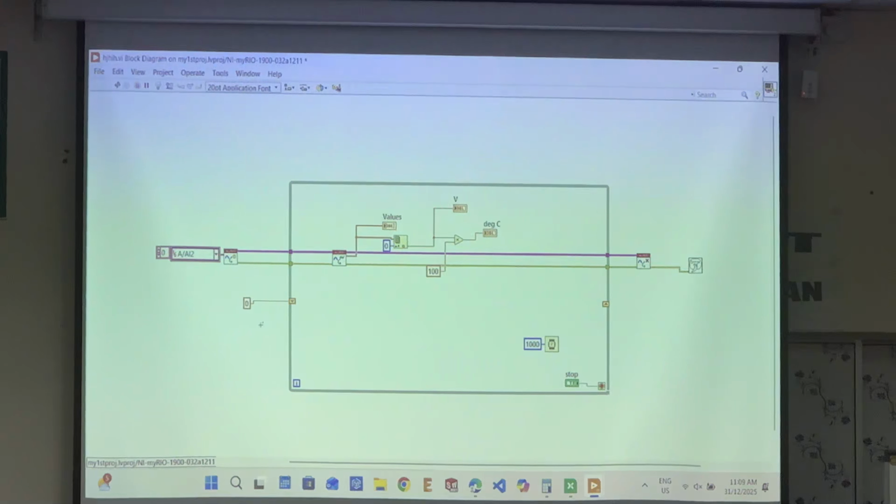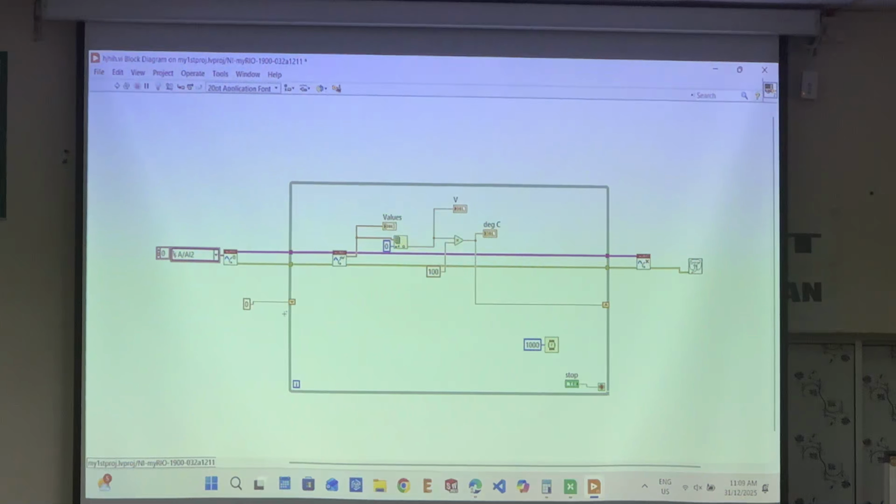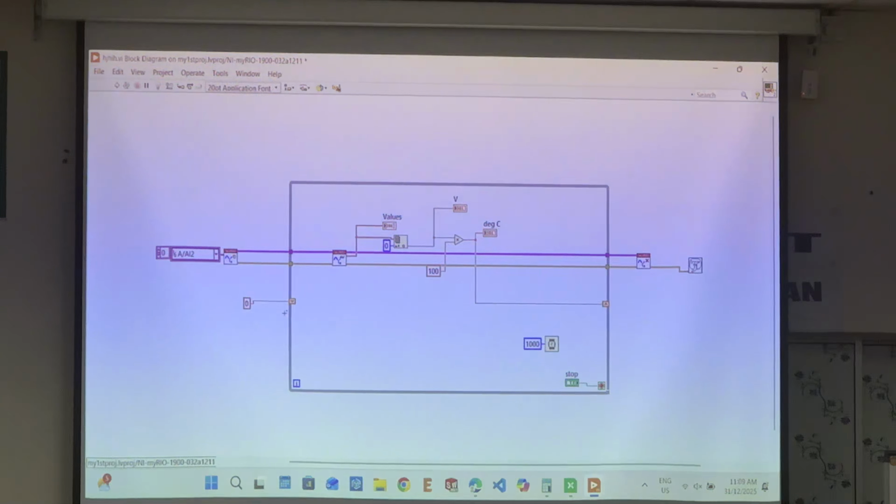Okay. So the role of the shift register basically is to memorize the previous data. So the first loop we run, we get the data. In order to get the first data, we have to wire whatever we have read from here into the register. The first data is 0. When the very first loop runs, the data of the register is 0, because we initialized it with 0.